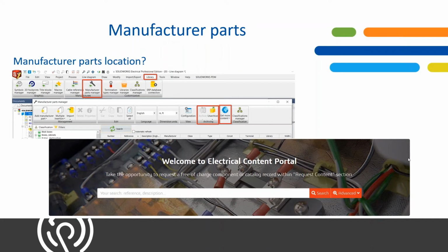So if you drop a motor symbol in, it's just going to show as a motor symbol on a line diagram. In order for you to carry over the right information and to populate all the information that you want to see into your BOM and your reports, you want to attach a manufacturer part to that. That manufacturer part is going to be connected to your SQL database, and that's going to be pulling over all of the information from your projects and all of your sheets.